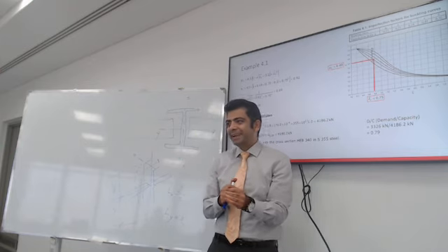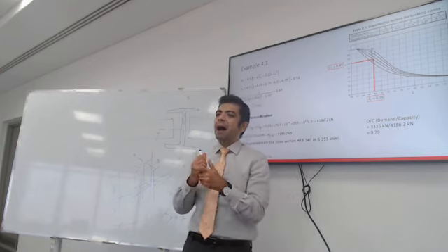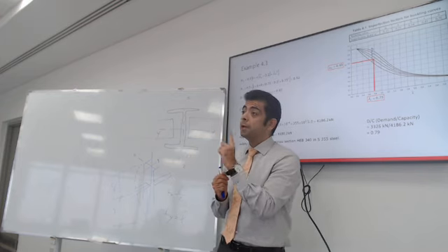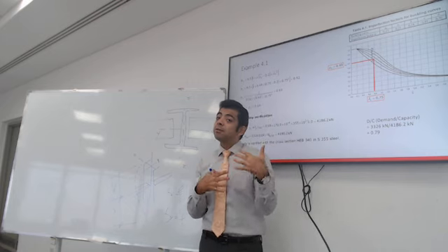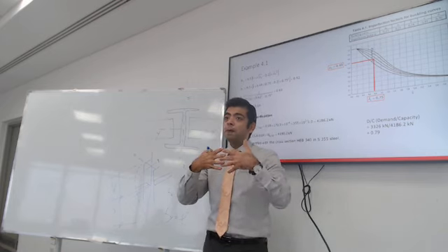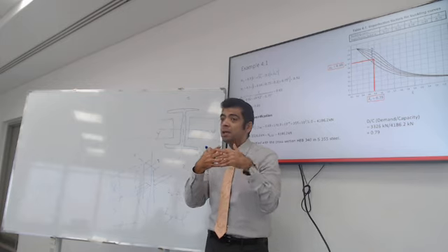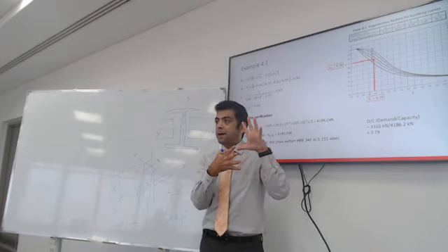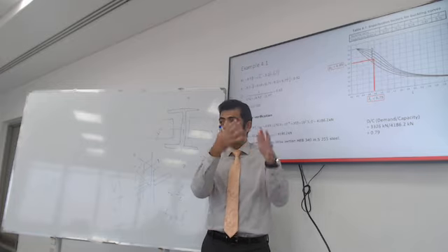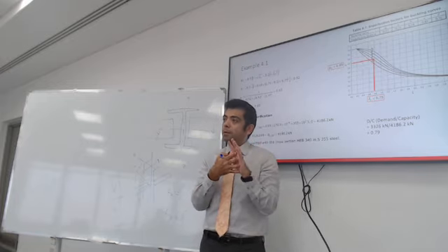Okay, I personally don't like to go above 0.9 because I need to leave some room for the design of the connections. If you design the member for 100% capacity, the connection might become very expensive. You can't actually fit enough bolts and welds to support that member.